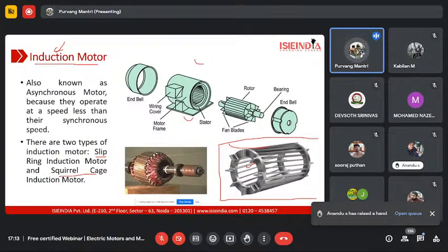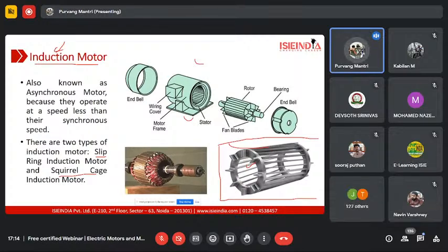There are different types of squirrel cages as well. In this case, only bars have been used, but there are other types of squirrel cage rotors where laminated iron sheets have been placed within the rotors. But one of the issues with the induction motor is that as the stator is inducing current and using the resultant magnetic field of the rotor to rotate the squirrel cage rotor, the initial torque is very low. It becomes pretty difficult to get the induction motor to start.